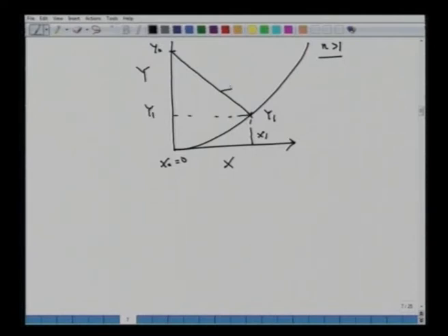Alright, this will be the slope of the line as minus SS1 over LS. So if we know this SS1, yes, we can draw this operating line. This intermediate concentration will be fixed at Y1. Unfortunately, we don't know it. Let's assume that this Y1 is known. Then from here I go to the second stage, take a different slope, minus SS2 over LS, to come down to this desired level of Y2, for which we have this